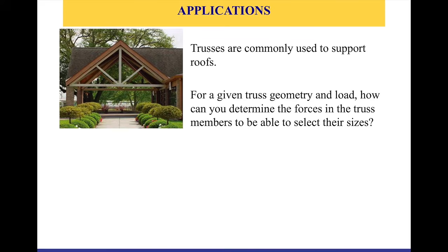For a given truss geometry and load, we'll have the question: how can you determine the forces in the truss members to be able to select the sizes of these members? Because this is one of the things that, as a structural engineer or a designer, you need to identify: how much force is in the member for a given geometry and load, and then you can select if you need to increase the diameter or increase the size of the members of your truss.